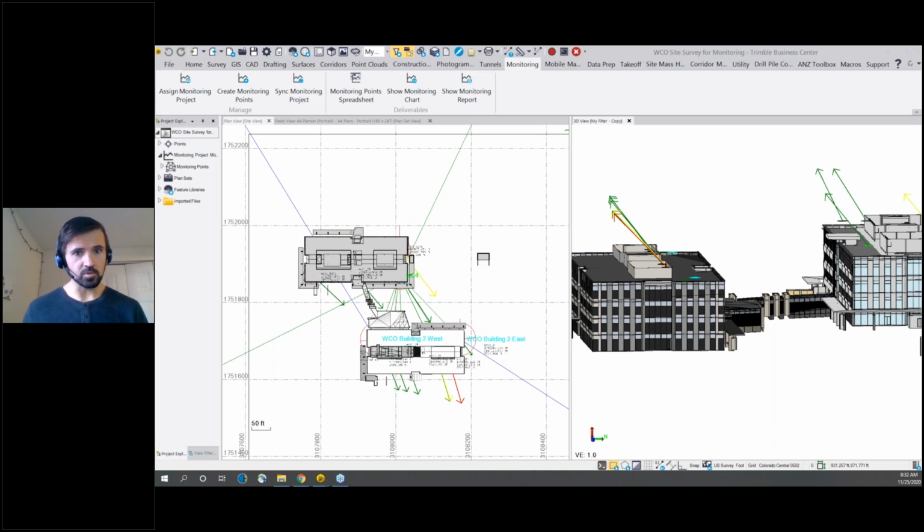And then another question from John, how do you combine conventional total station and digital level data on the same point if we're monitoring horizontal and vertical? So TBC, essentially, you merge by point ID.